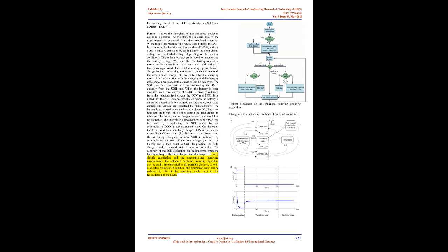The Coulomb counting method then calculates the remaining capacity simply by accumulating the charge transferred in or out of the battery. The accuracy of this method resorts primarily to a precise measurement of the battery current and accurate estimation of the initial SOC. With a pre-known capacity, which might be memorized or initially estimated by the operating conditions, the SOC of a battery can be calculated by integrating the charging and discharging currents over the operating periods.